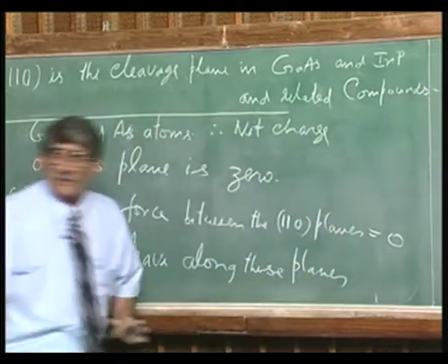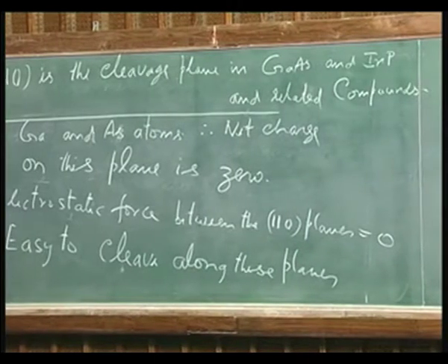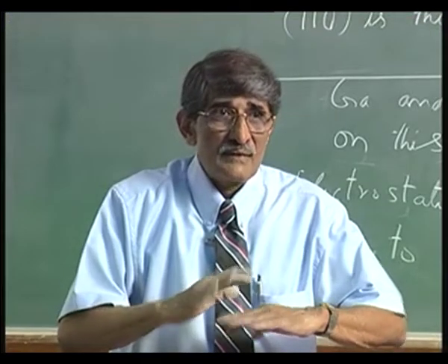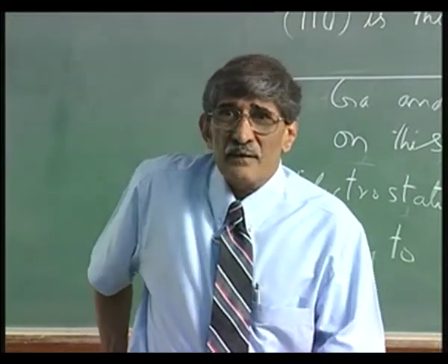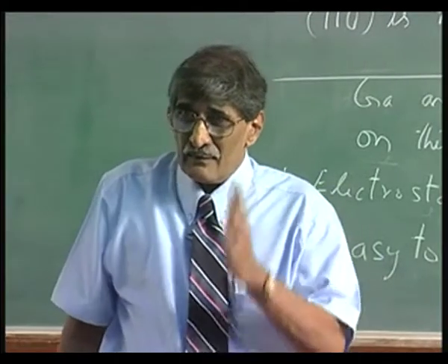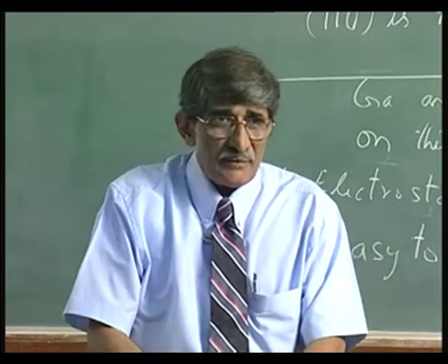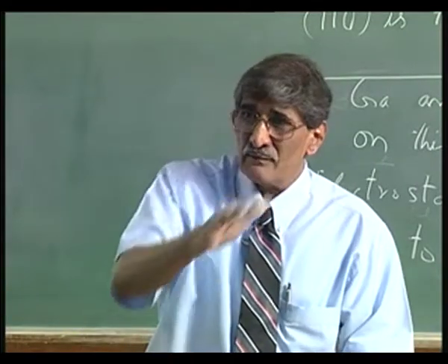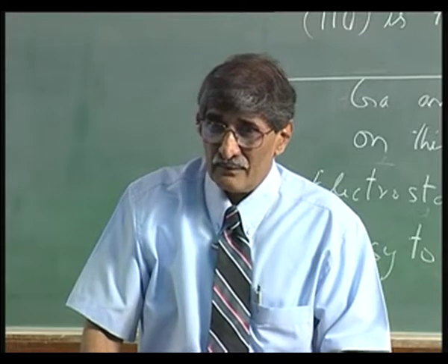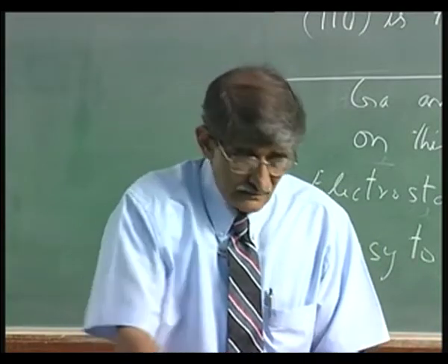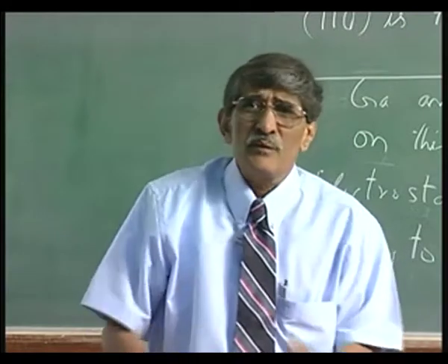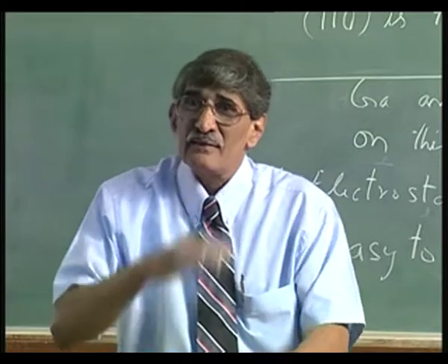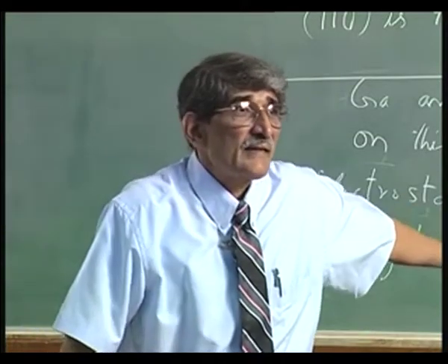Okay. So, this is what I want to drive home, because the entire idea of taking a look at this crystal structure is to understand some of the properties which are relevant to technology. And what is relevant to technology is, if I scribe and cleave in silicon, it will cleave along the 111 plane. Okay. How do you cleave? You just draw a line, scribe to a depth of about 1/10 of the thickness of the wafer. Then just apply a little bit of force, it will just cleave along that plane. That is what is meant by the cleavage plane.